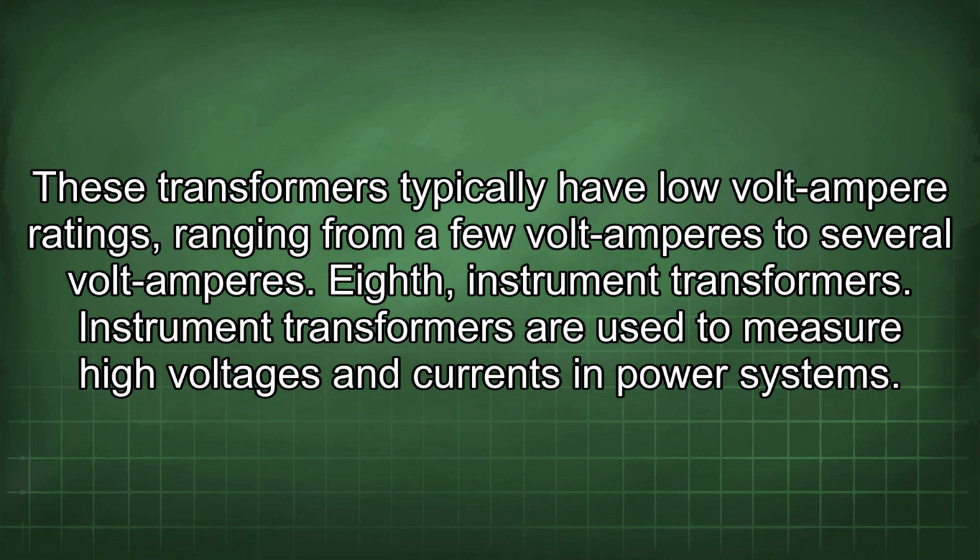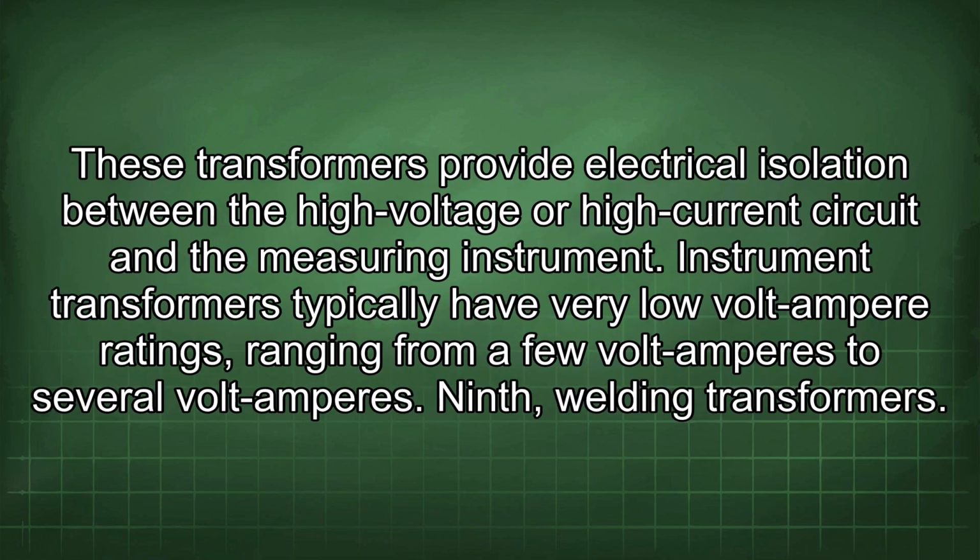Eighth, instrument transformers. Instrument transformers are used to measure high voltages and currents in power systems. These transformers provide electrical isolation between the high voltage or high current circuit and the measuring instrument. Instrument transformers typically have very low volt-ampere ratings ranging from a few volt-amperes to several volt-amperes.